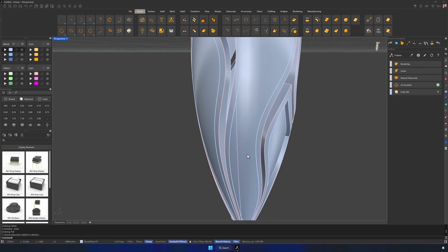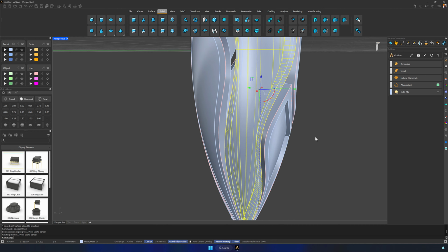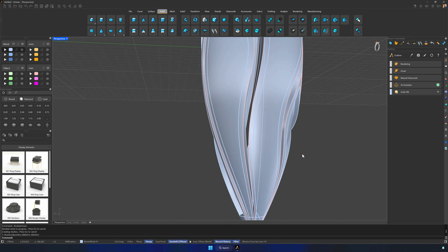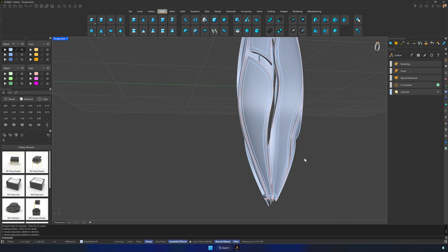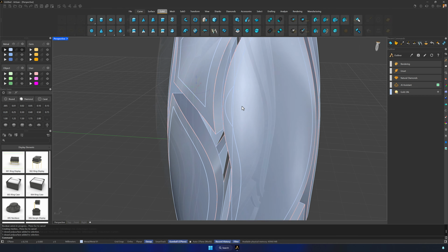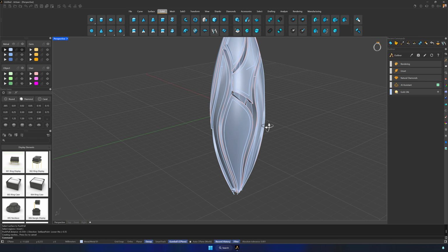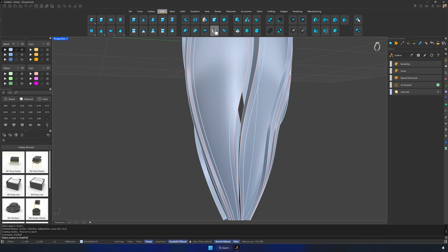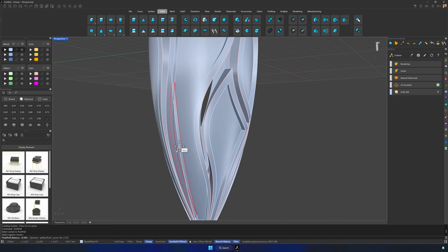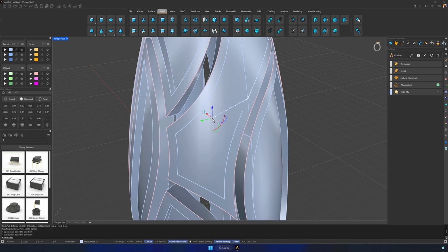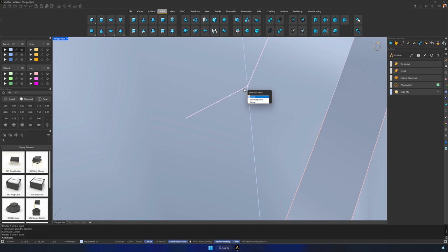In this case, I realized that I had two separate solids, which is why push and pull was not working correctly. So I used the Boolean union command to merge the two parts into a single solid. Now, we do 0.35, and it works. We keep going. Projecting, pulling, moving points when needed, joining curves, and repeating the push and pull until all sections are created correctly.